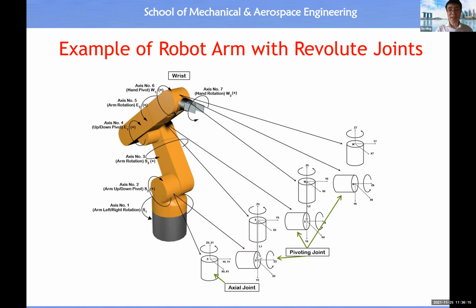Okay, later on we'll come back to this convention, I guess in lecture 3, when we study the design of a robot mechanism. For now, just keep this background knowledge in mind, that should be good enough. That means for every link, there's a local coordinate system, and we use the z-axis of the local coordinate system to indicate the axis of rotation provided by the joint or by the motor. So this is the example, and you will see Z7, Z6, Z5, etc.